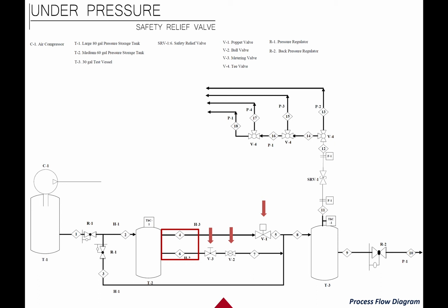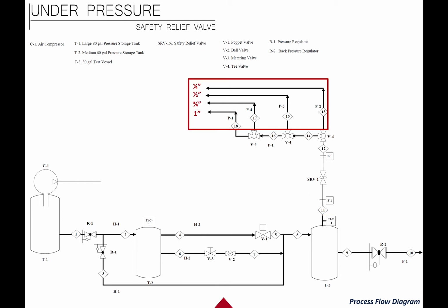The pop-up and ball valve have an electric actuator attached to them that can be controlled through LabVIEW. A back pressure control regulator is placed on the drain pipe in Stream 9 to maintain the pressure under normal conditions. In Stream 11, the air enters a safety relief valve that discharges into a T-valve, where the student gets to test which vent line should release the air.